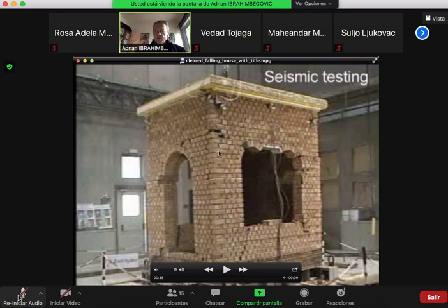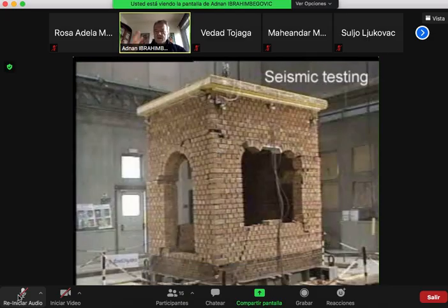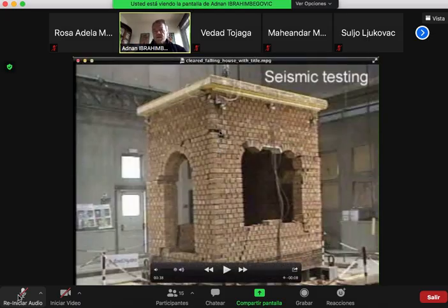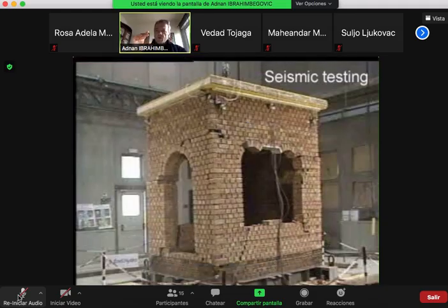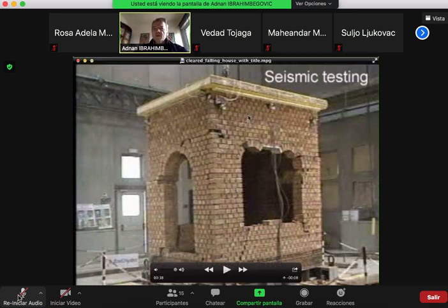So you cannot do real-life testing here, because on the shaking table you cannot put unlimited weight. You put only the weight you can afford, which you can then move to simulate the earthquake. So you have real earthquake simulation, but you don't have the real size of the structure. So you really get into the problem of how to estimate the real size of the structure. And this is the problem that one has to worry about: when you get an estimate on something very small, how to get the true behavior of something very big. And this is a serious problem.